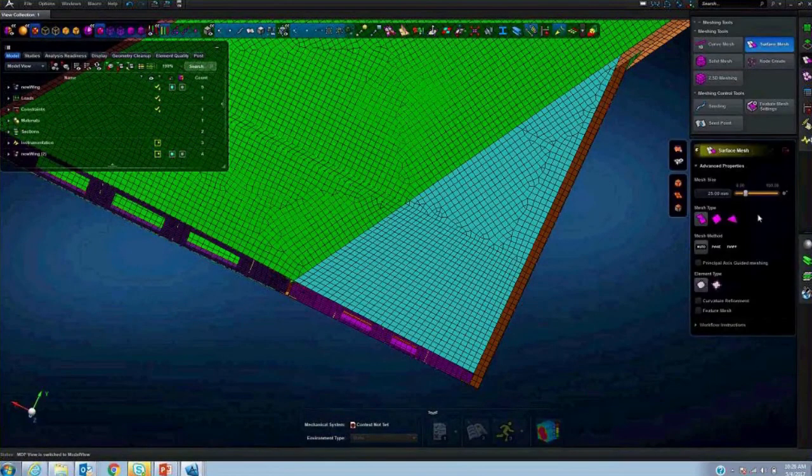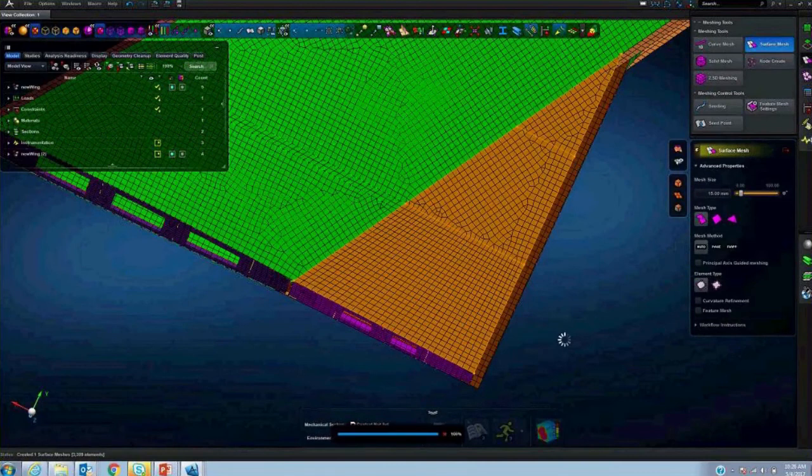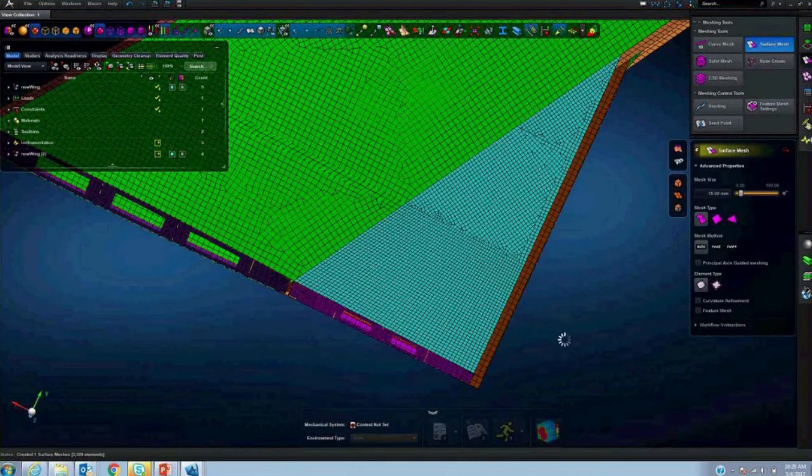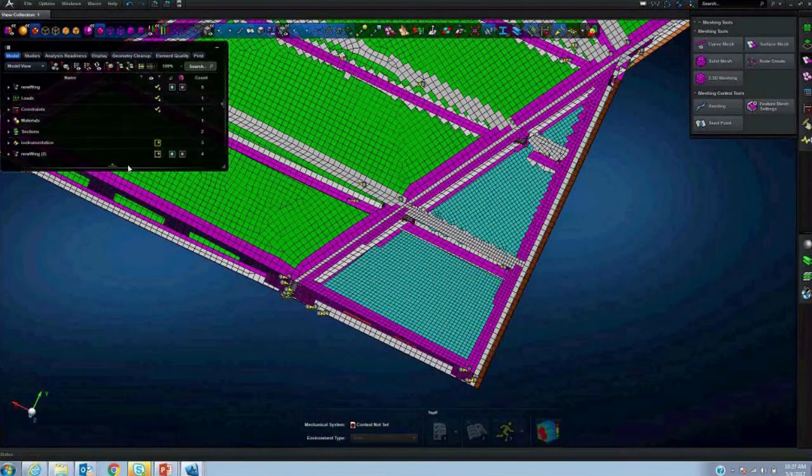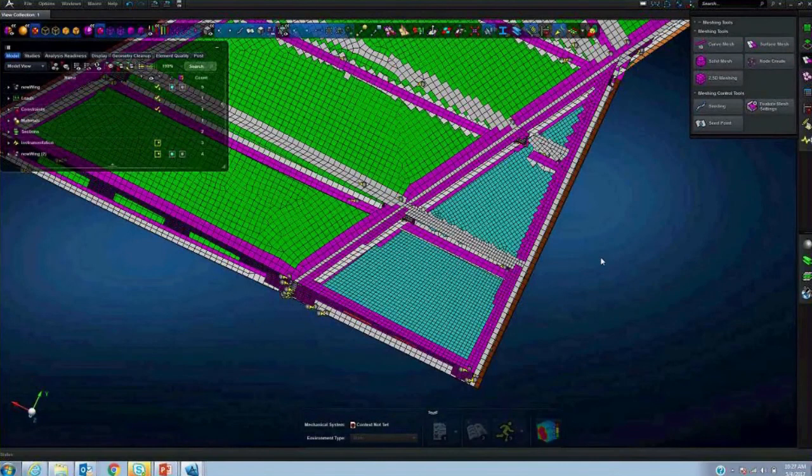I can go to the mesh tool and make this mesh, for example, a finer mesh, and pick that face. Now you can see that the local area of the buckling model has been modified with the refined mesh. And all the generated behavior, for example, if that panel was connected to the rest of the model, all those connectivities, in this case through glue, got updated. Now, it is as simple as setting the context again and running through this buckling.